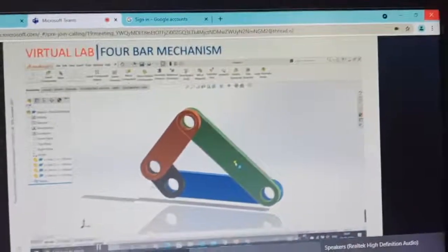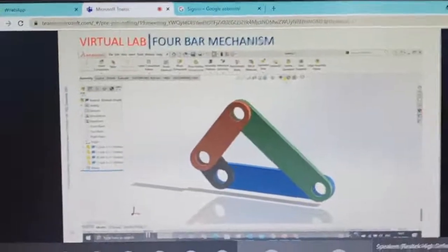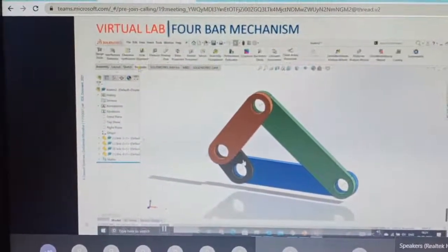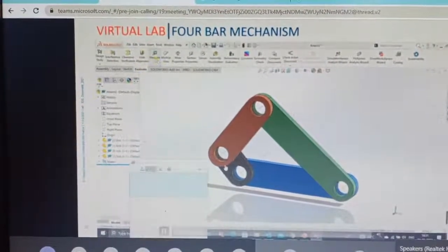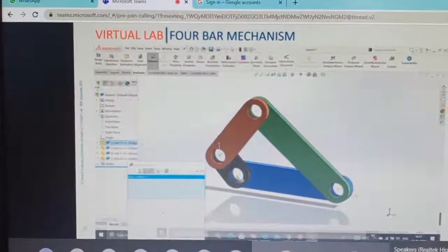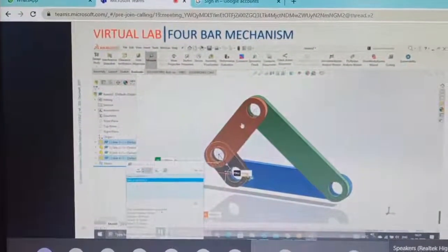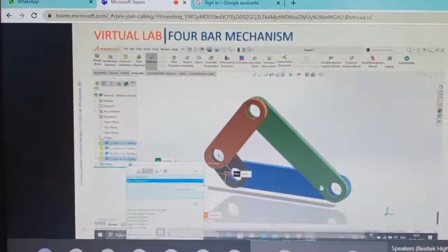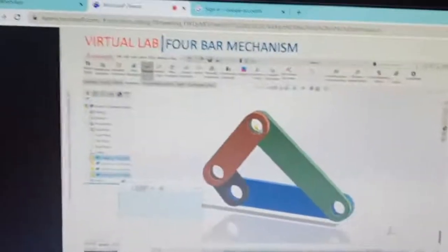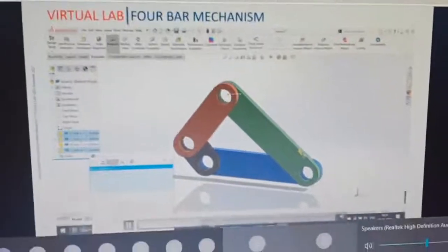This is the rocker thing. So for complete rotation, what is our requirement? For complete rotation, our requirement is that the addition of this distance and this distance, from here to here, should be less than or equal to the total distance between these two components and these two components. Okay, so I'm also going to show you the dimension from here to here, that you can also see.